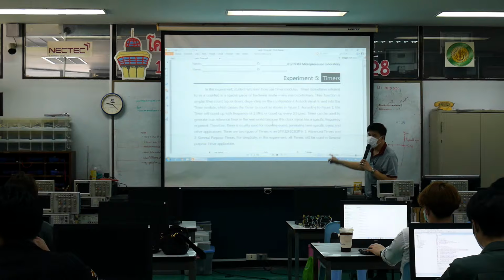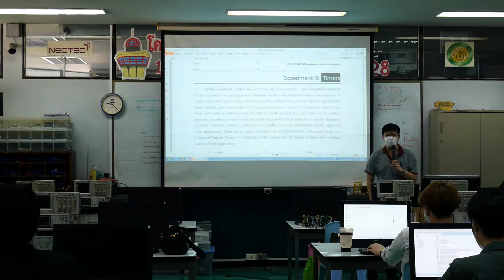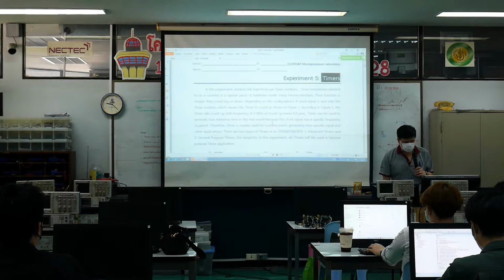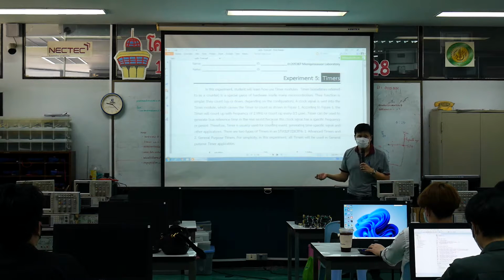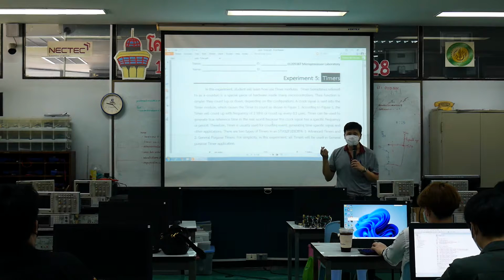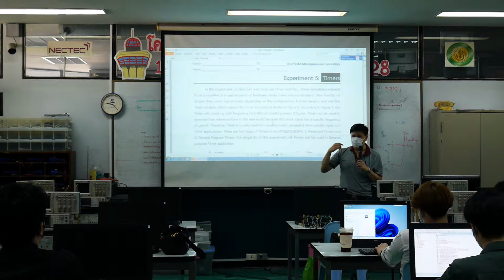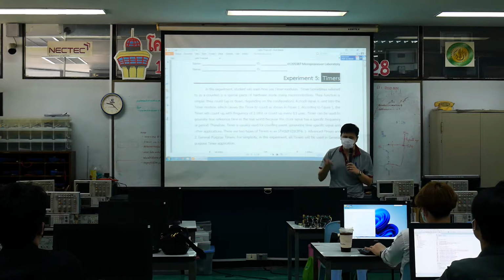But in today's class, we will do some experiments on timers. Therefore, if a timer is related to real time, what does it mean? It means that when you use it, you can create any kind of time. So what is the time that we want? It depends on the applications, and today you will see at least 2 applications. The first one is the time itself. You will use a timer to create a delay function, a very precise delay function. So if you want this delay to be 1 millisecond, you can use a timer to generate 1 millisecond.